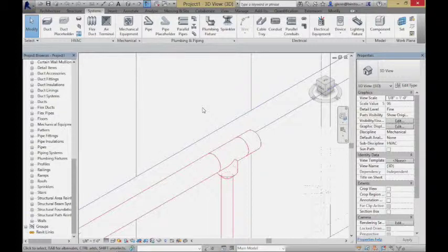What Revit's really good at figuring out is, if you've got a 4-inch pipe and a 2-inch pipe, how to connect them together. It's good at figuring out what sort of elbows and connections and transitions it needs to put between those things. But in terms of the actual routing locations, if it guesses wrong, don't be afraid to tell it otherwise. Because like most computers, it's only as smart as it can pretend to be. There's no easy way to do it completely automatically.